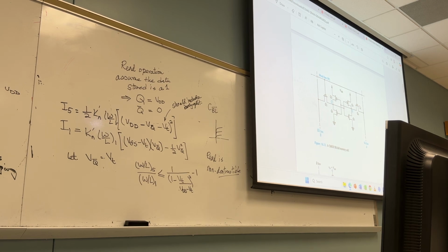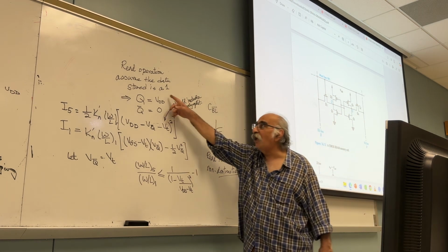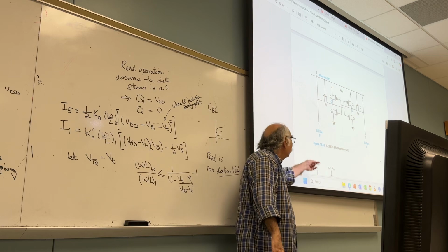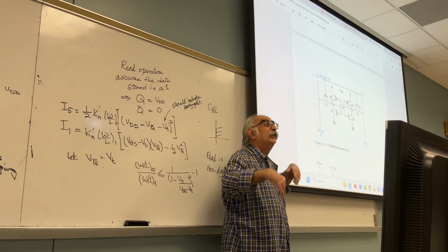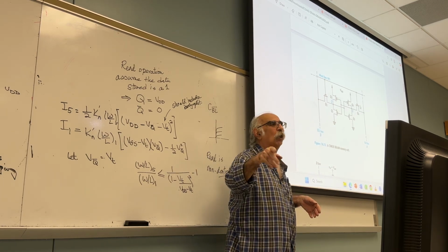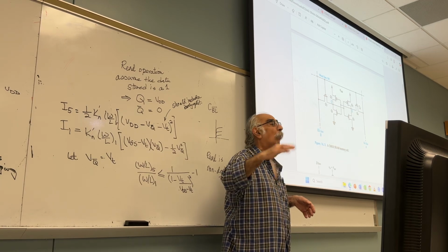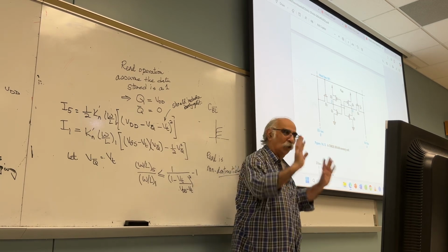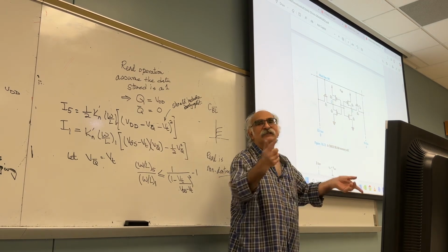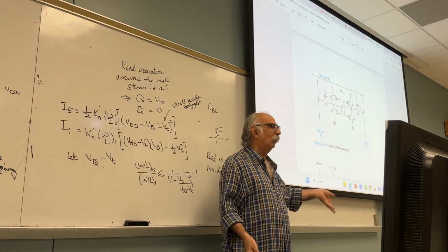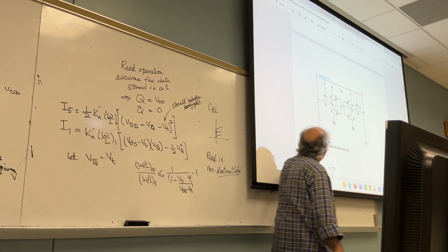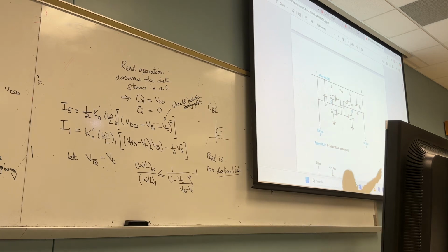Yes. Okay, question. Could I have charged the bit line and the bit line bar initially to VDD over 2 instead of VDD? Yes, I could have. What happened? Can you tell me what happened? If both of them are pre-charged to VDD over 2, both sides will conduct.